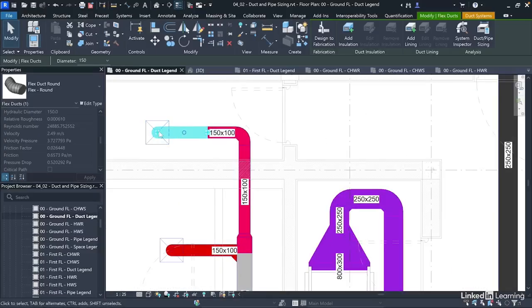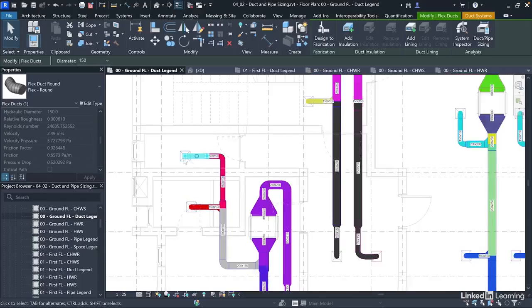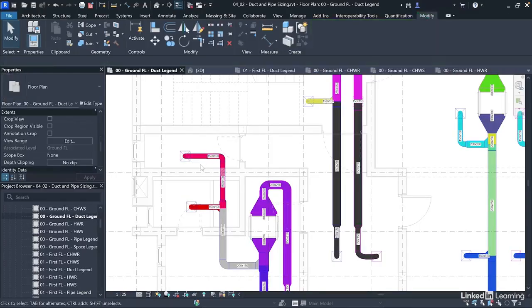If you want this to fit in properly, you can either increase or reduce the neck size of your air terminals, or you have to cushion the effects of maybe too much friction or too much velocity. The velocity here is slightly out of range, is 2.5 that we need, and the friction is actually correct. So this is actually fine, but in such instances, you either increase or reduce your neck size, or you find something else to join both of them.